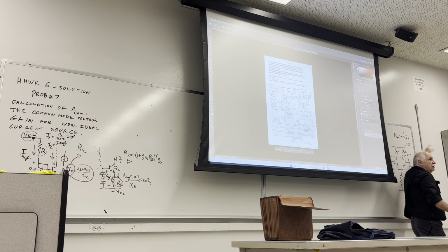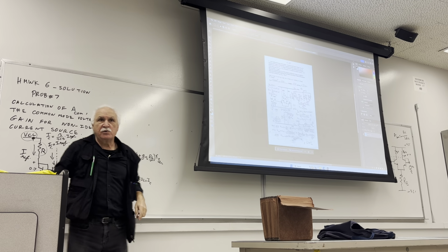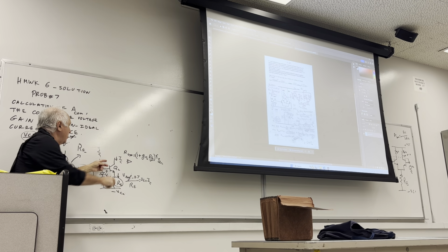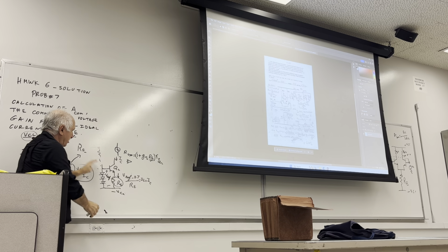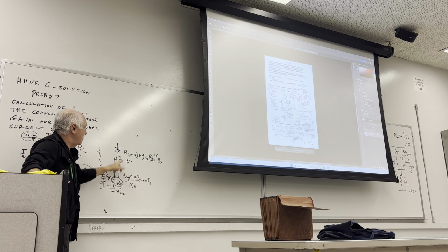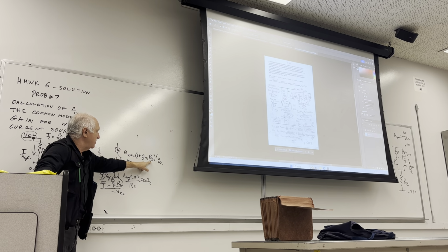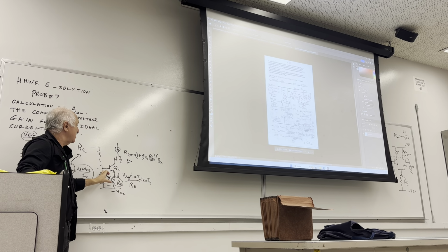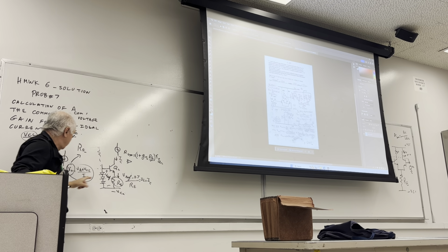If you had this arrangement here, a better one, with that transistor replacing the current source, because now the collector is sourced with this arrangement, then the dynamic resistance here would be 1 plus gm of that transistor times the RE that you're placing in the emitter path, multiplied by the dynamic resistance between collector and emitter, just like before.